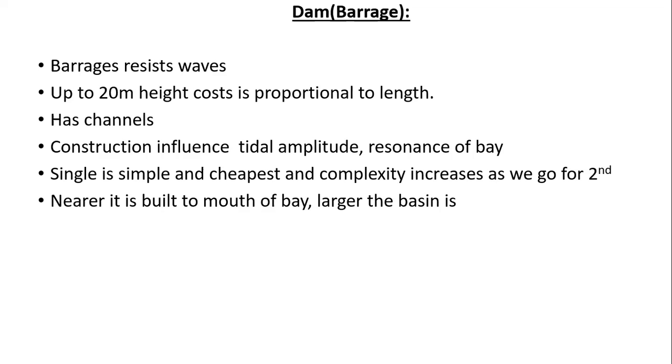Tidal power barriers have to resist waves whose shock can be severe and where pressure changes continuously. So these have to be rugged to support the water resistance. Since barrage length also adds to the price tag of the plant, short barrages are preferred, because the cost can increase to such a level that it occupies one fourth of the power plant. Short barrages are preferred even if the basin size may have to be smaller as a result of site choice.